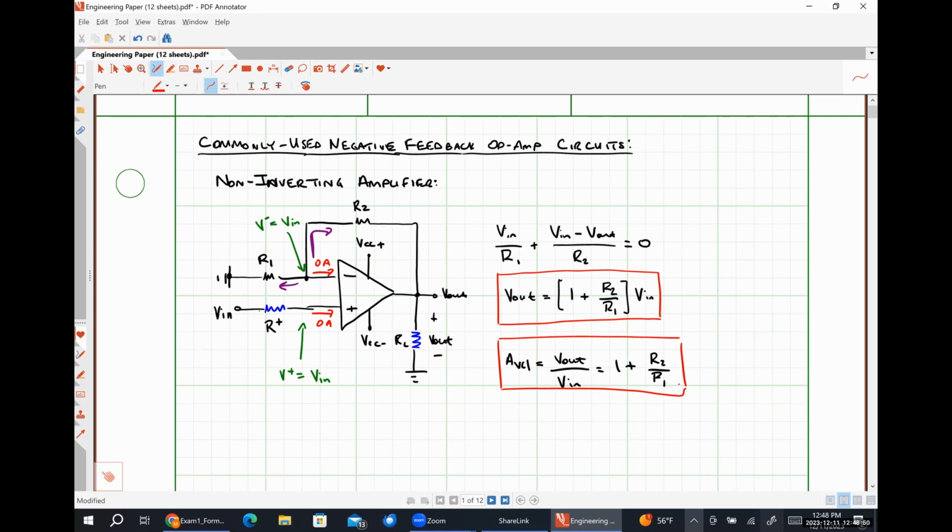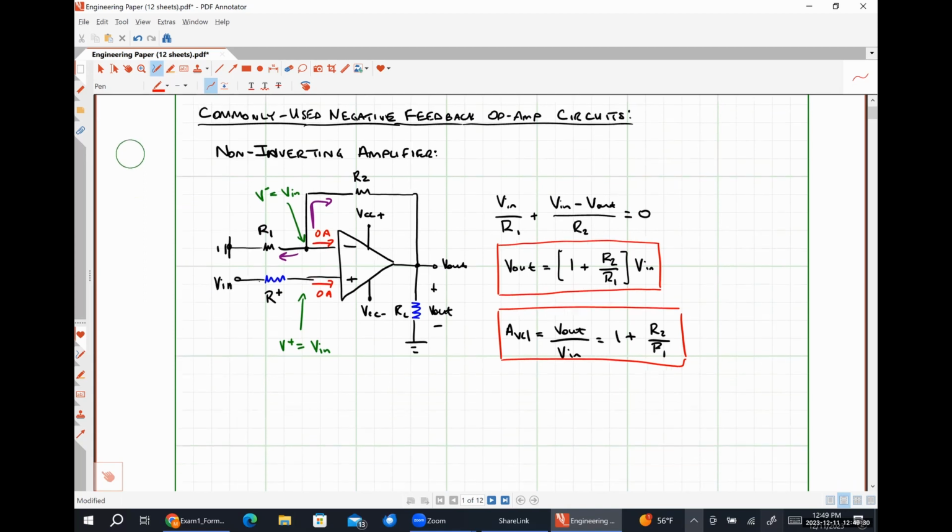And let's say that you're trying to measure brain waves or something like that. The transducer that measures things typically can't supply large amounts of current. So exactly what Toby said, if you use a unity gain buffer, that's making sure that all of the current that's needed comes from the op-amp power supplies and not from the source itself. Unity gain buffers are a very important stage in practically any instrumentation amplifier used to measure real world signals. So if you're measuring things, unity gain buffers are usually your first stage. Very, very good answer.